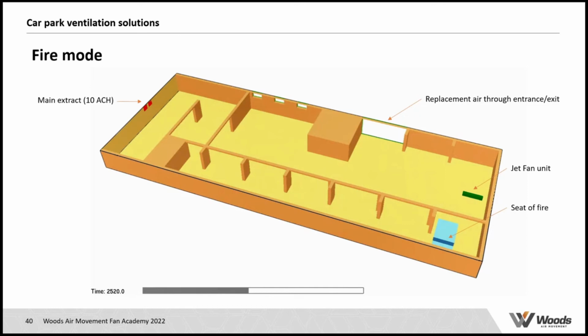The reason for putting the emphasis on that is that you can't expect any conditions in the car park. Again, it's solely there to start extracting smoke from the car park, so that at some point you'll have sufficient visibility, for instance, for the firefighters to do their structural survey and things like that. So it's important to understand that 10 air changes is really only a ventilation system.